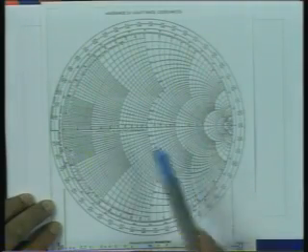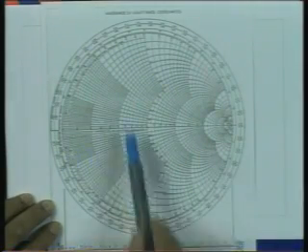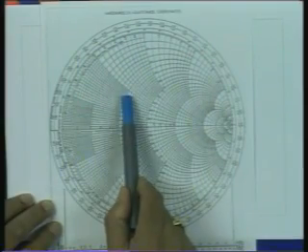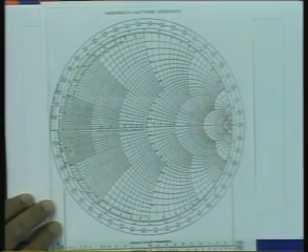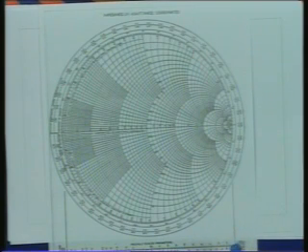So, every time, without going into the transformation, I can read from this itself the values of r and x and directly mark an impedance point on the complex gamma plane. This is an extremely powerful tool, what is called a Smith chart, and now we will see how this Smith chart can be used for doing various types of transmission line calculations.